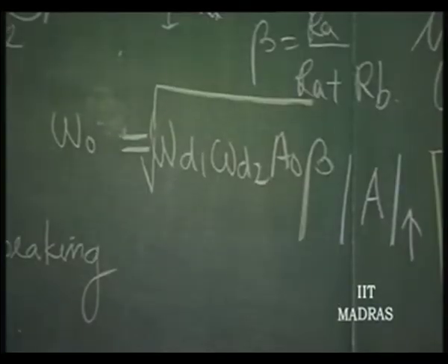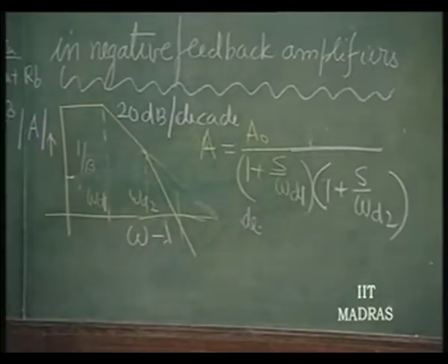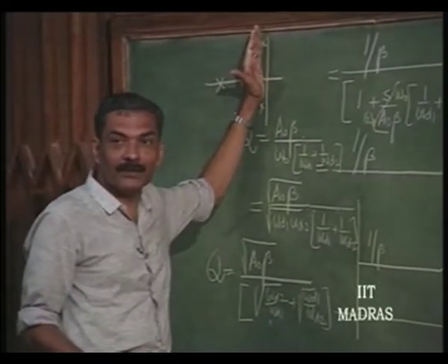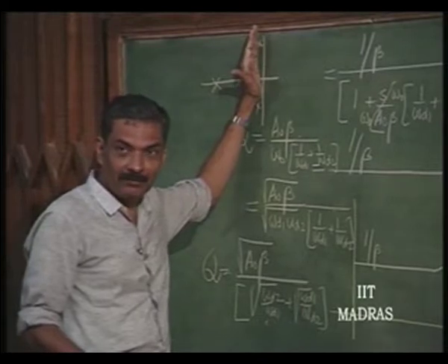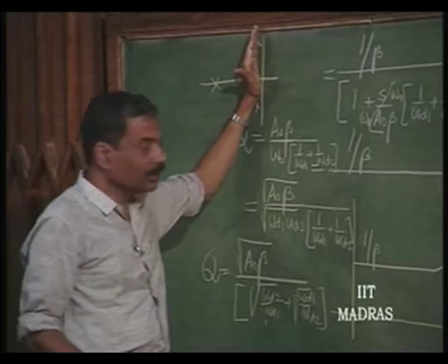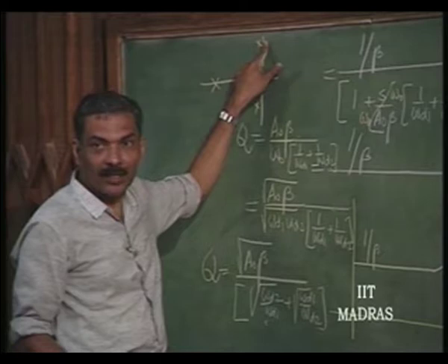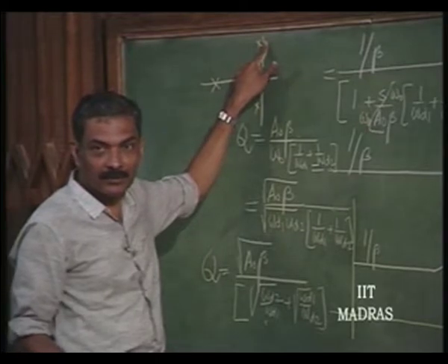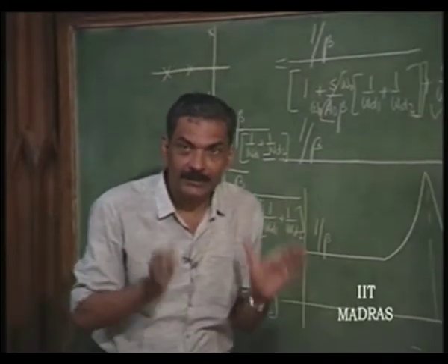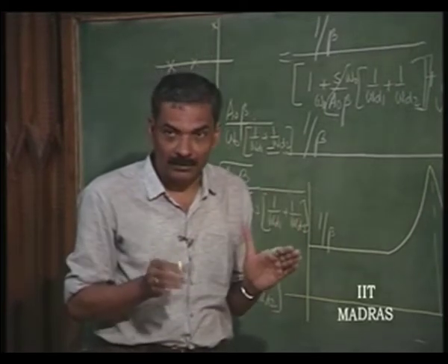That means, by the time the system has a second pole, the system is now going to be very nearly on the verge of instability, because if we now have additional phase shift caused by an additional pole, then this can shift to the imaginary axis and the system can become unstable. Right. So, this is the problem, that a negative feedback system is stable as long as the order of the system is second order.